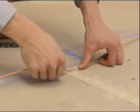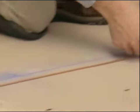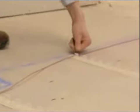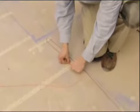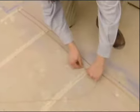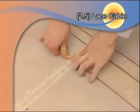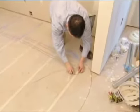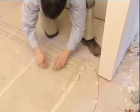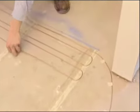Close the first 1 or 2 hinged clips on the strapping in order to hold the cable securely before proceeding to the next strapping run. Subsequent clips should be left open until cable placement is completed. Wind the cable at appropriate intervals and snap into the strapping slots. Then carefully turn the cable and snap into the next appropriate slot. Note: do not extend cable beyond the edge of the strapping.